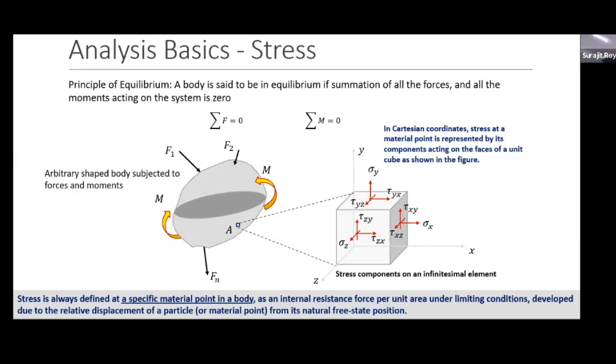For other applications, whether commercial, machinery or some other components, you will typically find a factor of safety close to 2. But for aerospace structures, the factor of safety is around 1.25, or a max up to 1.5. You said 1.5? Max, yeah. That's probably to save weight and cost, I guess. Weight is the most important concern for aerospace structures. How can you have a higher strength for a low weight design? That's always the concern.